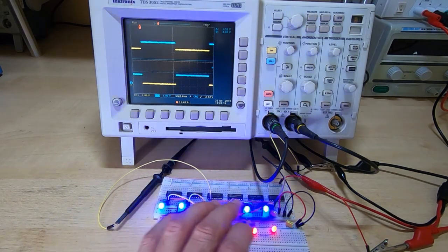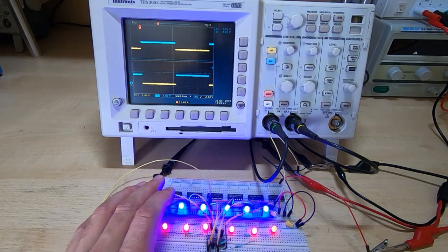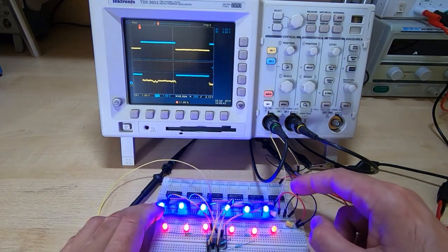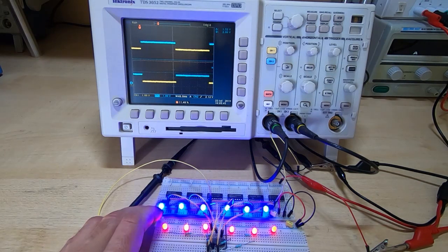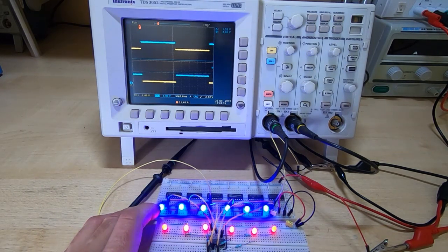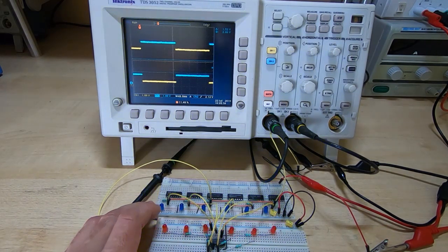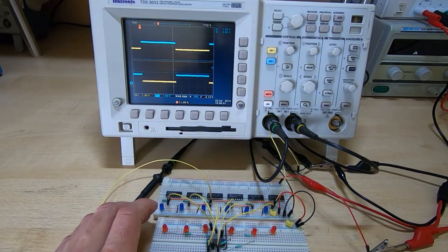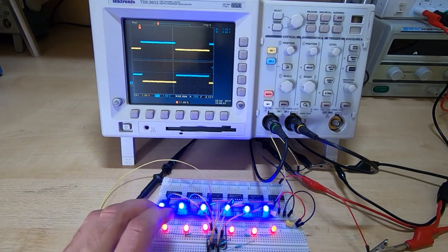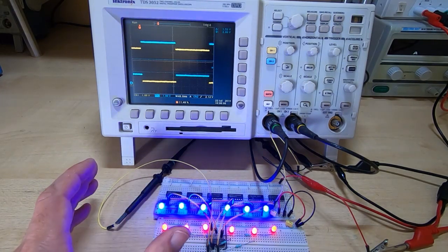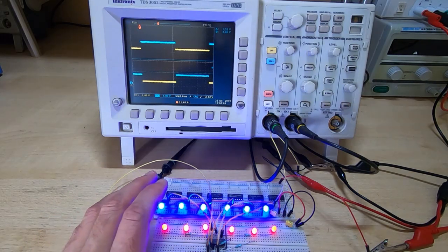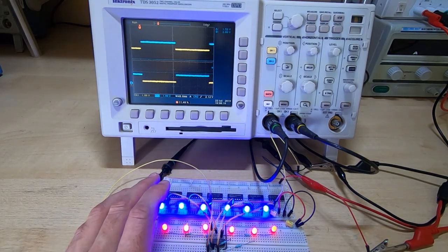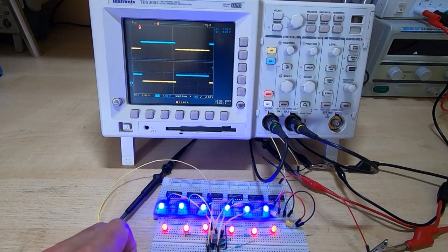This gets even worse if you do want to try this experiment. It is quite interesting, and it will get even worse if you start moving the ground lead supply around. And this comes back to the previous video I made on designing the board for the Altair, in that using a ground plane can eliminate a lot of these issues where you get this strange interaction. So quite often it's not just a case of, well, it's better for the power supply if you have a ground plane. A lot of the time this can just be a simple case of preventing odd interaction between various